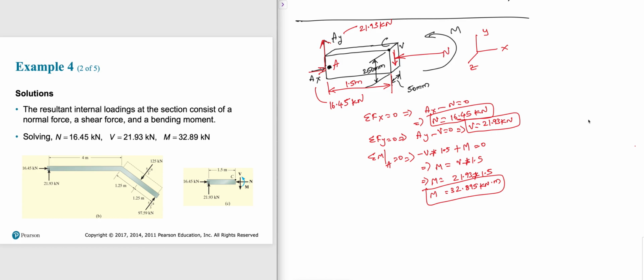So what I'm trying to write is, what is sigma C? That means, what is the stress at C? The way we can find it is due to normal force over area, right? Yeah, normal force over area, and this is negative because normal force is a compressive force.